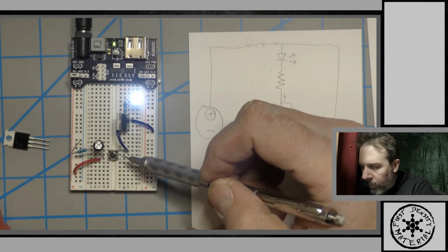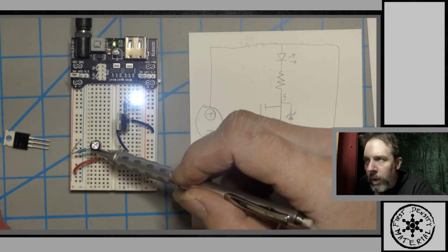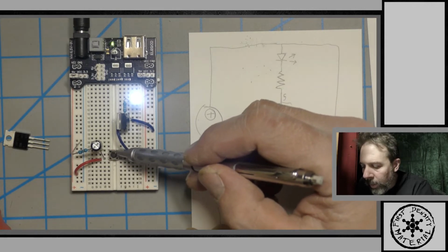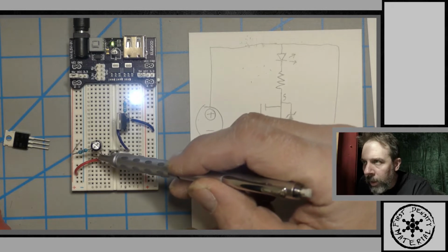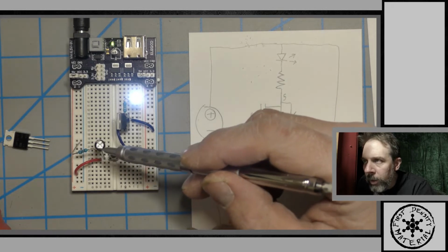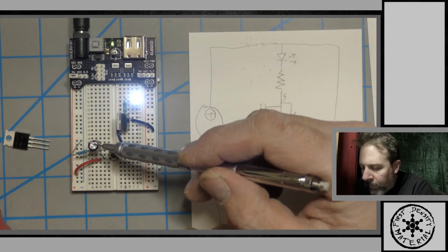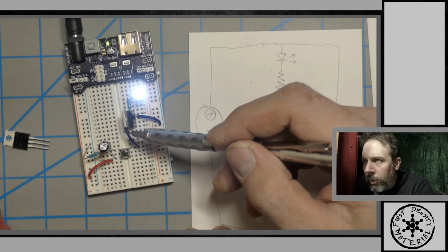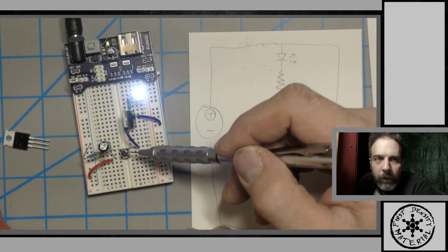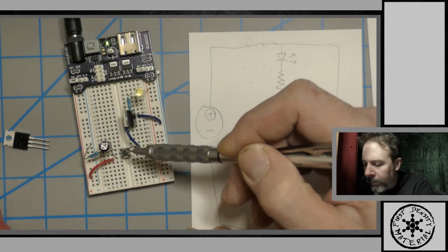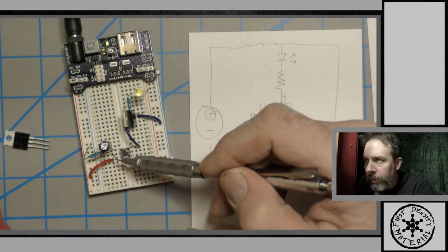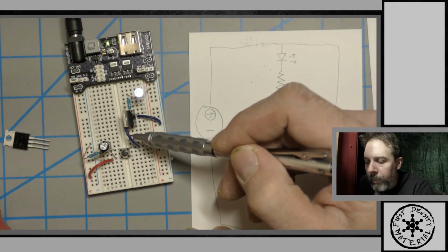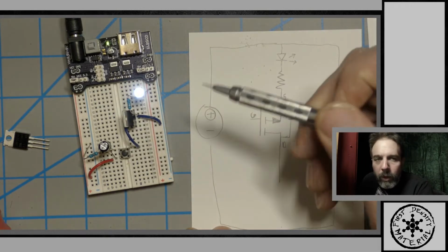And now we have to deal with this switch. The switch is kind of complex in a way because we know that this area right here is all hooked together. So you're looking at a resistor and the negative leg of a capacitor all being hooked into the gate even before the switch is pressed. By clicking this, that's making this positive, and it goes in and hits the gate. Therefore, it turns the LED off.